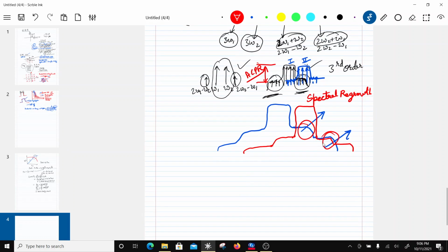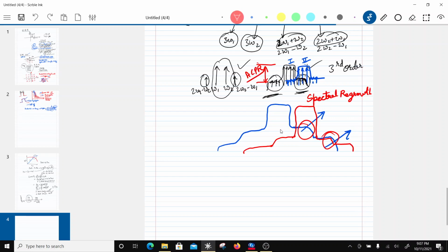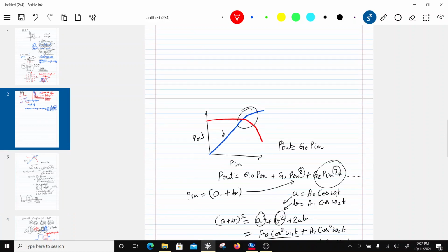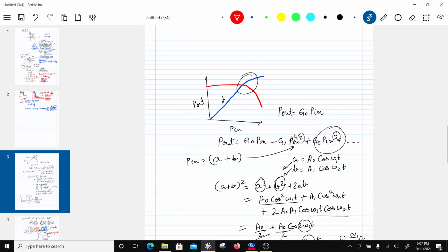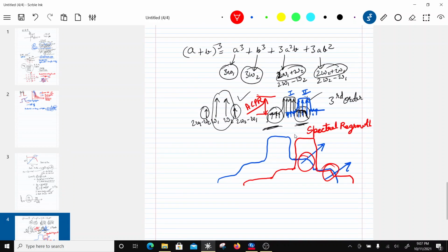One more thing I want to mention is the channel bandwidths and the guard band. If there is a guard band, that's helpful, right? If there is no guard band, then this is a severe case, and it's purely dependent on the linearity. There's no way you can filter this out, because you would require a parametric filter shifting channel by channel with very sharp cutoffs. So basically you will not be able to get rid of it through filtering.